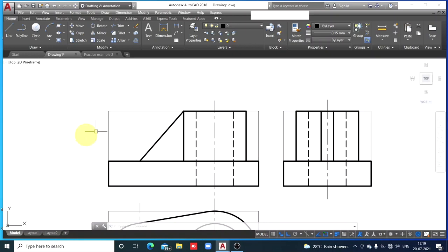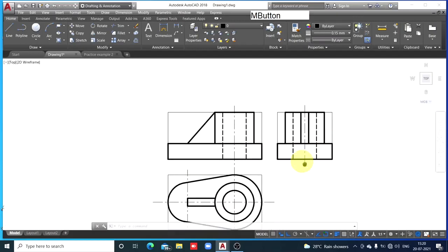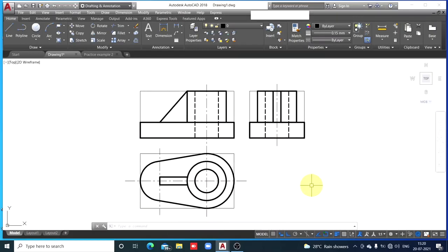Now from the left side, this is the left side view, the observer is watching from left. So this triangular plate is visible. So don't draw this triangular plate hidden, it's visible. So dark continuous lines are correct. Had it been this triangular plate on the right side, then we would have concluded that triangular plate as a hidden plate and we would have drawn these two lines dotted. Okay, so this is how we have completed the drawing.